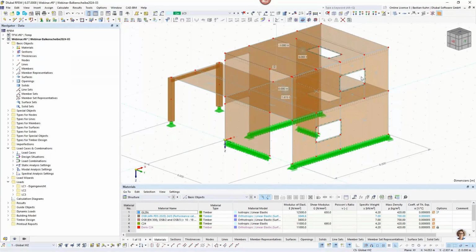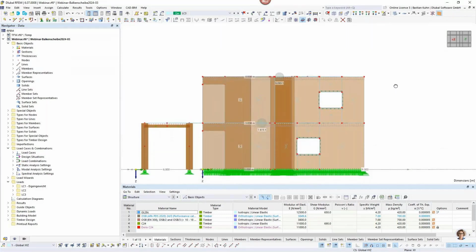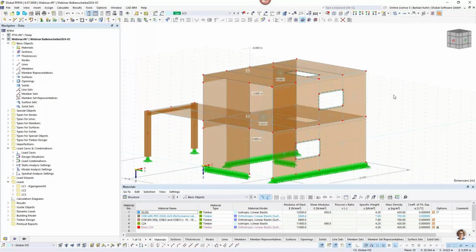And this is for a hand calculation. And what would you do when you calculate such a structure by hand? You would calculate your horizontal force, and then you would say, okay, this surface cell will bear this horizontal force, and this surface cell this, and I need anchors here and here at this point, and I'm totally skipping the elements in here.